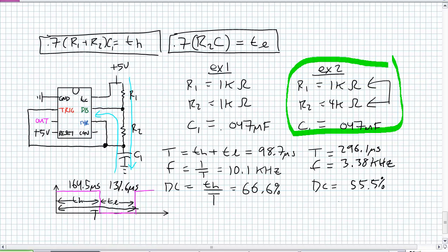Okay, so there is kind of a cunning trick to this, and the point is basically look how it's charging. It has to charge through two resistors. For duty cycles less than 50%, we only want it to charge up through one resistor, and how you do that is just offer a side path to it. You've seen a device in semiconductor devices and circuits, namely a diode. I can put a diode in this configuration and watch what happens when it's charging now.